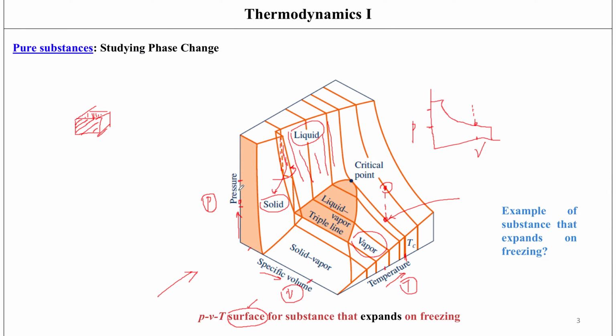What this means is that if I was to decrease or increase the specific volume, and if I'm decreasing the specific volume, and my pressure is increasing now, it would be a sharp jump up in pressure for me. Okay. And why is that? Because water or liquids are very hard to compress. So that means the rise in pressure is really steep for these kinds of substances.